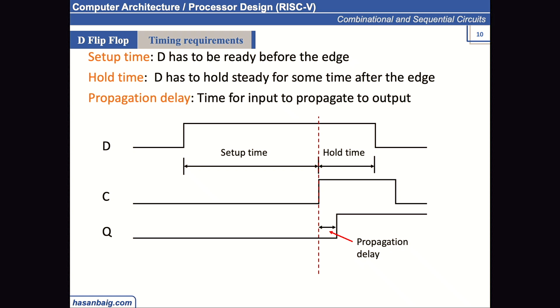When he's looking at me, at this instant of time, which means the positive edge of the clock, he cannot grab the data immediately. So I cannot provide the data right at the positive edge of the clock. I have to make the data available way before the positive edge of the clock strikes.